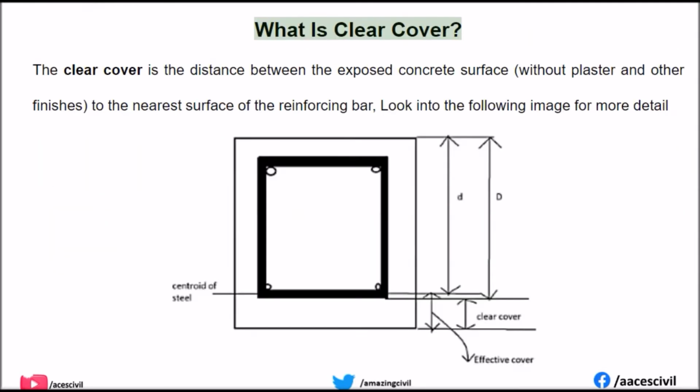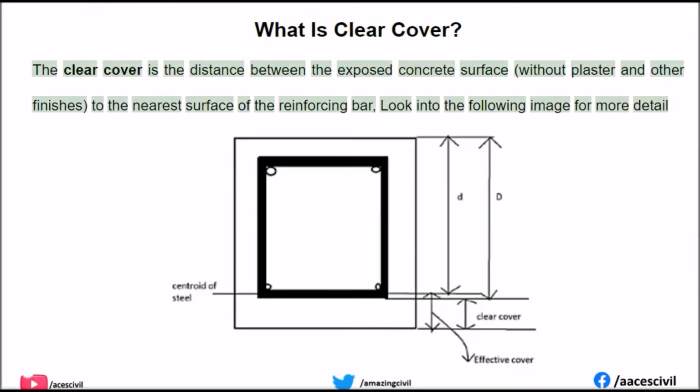What is clear cover? The clear cover is the distance between the exposed concrete surface, without plaster and other finishes, to the nearest surface of the reinforcing bar. Look into the following image for more detail.